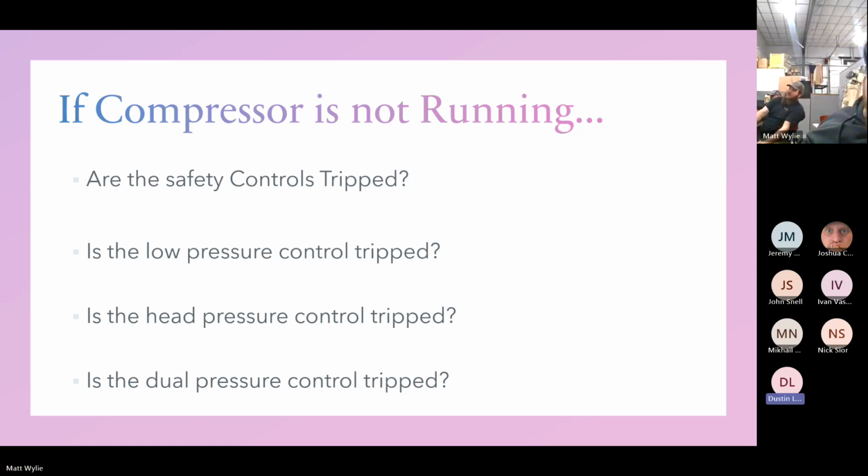So let's say it's 120 and it's closed, you have 0 across it, right? What do you have to ground on each side? 120 to ground on each side. So what if it's 208? What do you have across it? Nothing.